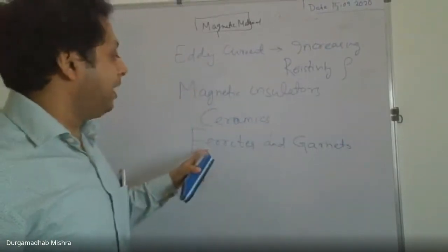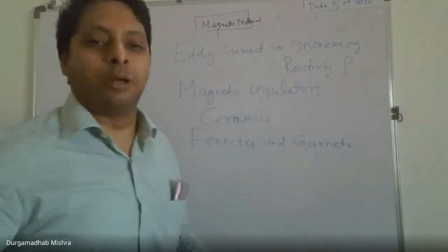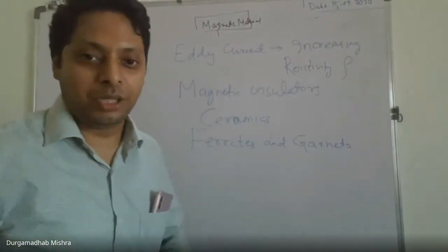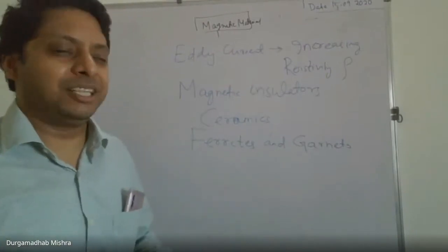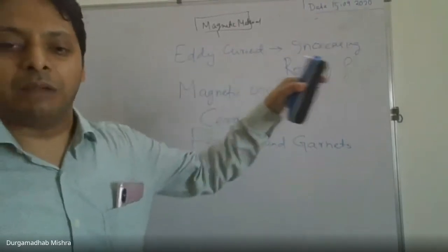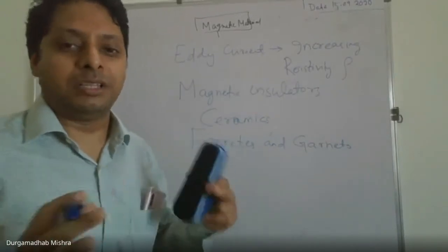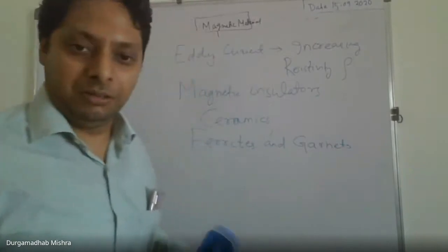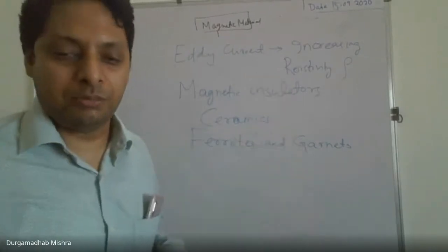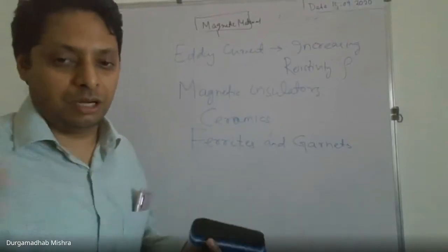But of course, why don't we use only ferrites? The reason is that for low frequencies, when we are working with 50 hertz or 60 hertz, which is what we commonly work with, electrical steel, which I wrote in the beginning, these iron carbon or iron silicon compounds, are cheaper as well as work with relatively good efficiency. Of course, ferrites will have better efficiency than those materials, but still the price will be higher. So we use this steel material for normal application.